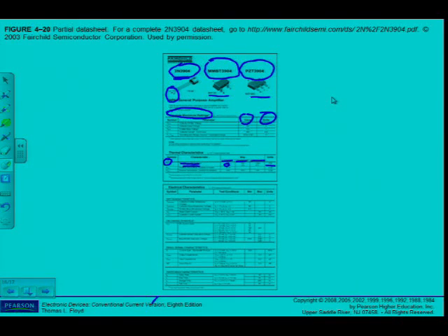Right, another important thing from the data sheet that I just want to point out is the ON characteristics. The first thing there is the thing that we have mentioned earlier, HFE. What is HFE? Beta DC, no? It's the DC current gain. Now what is important, you can see on these tables are indicated minimum, maximum, and units. Okay, so it's regarding these tables down here. So what do I note for HFE?